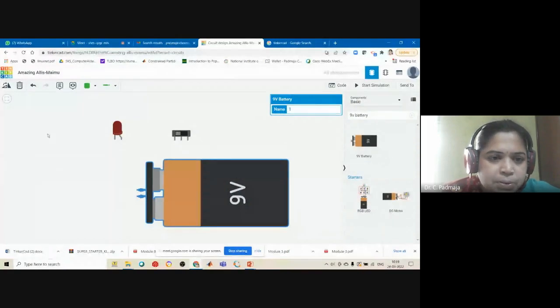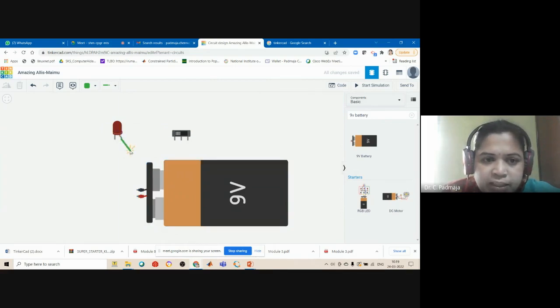Suppose I see this particular LED: the leftmost lead is the cathode terminal and the rightmost one is the anode terminal. And similarly, this is my switch, which consists of three leads. The leftmost is terminal 1, the rightmost is terminal 2, and the center one is the common, so that is a ground with respect to that. Okay, so suppose I connect this to